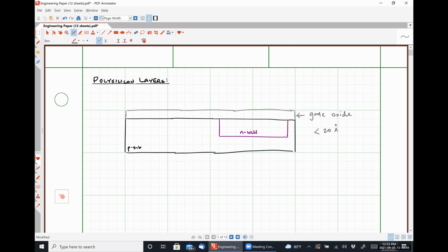Yeah, so it's a tenth of a nanometer. So it's a very, very small unit of length. So our gate oxides are typically on the order of 2 nanometers. So we're talking like 5 to 10 atomic layers thick. So it's a very, very, very thin oxide.